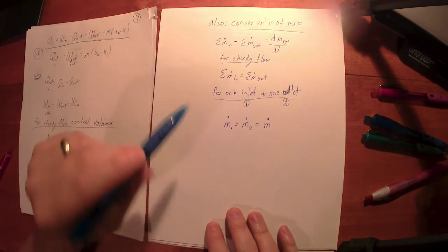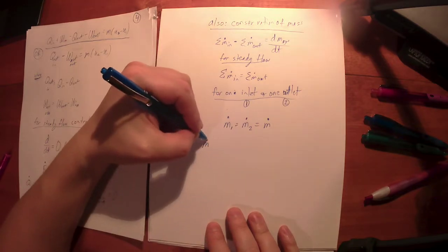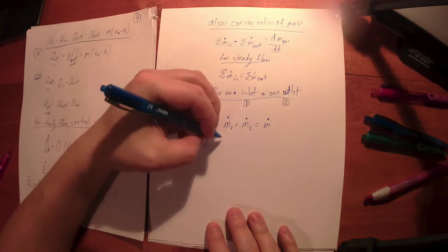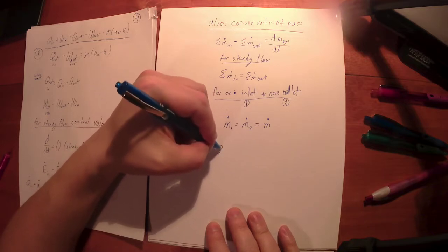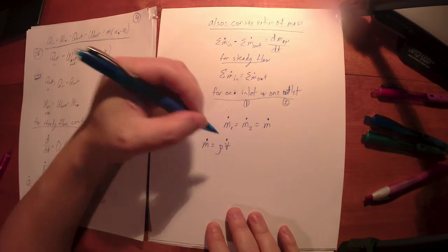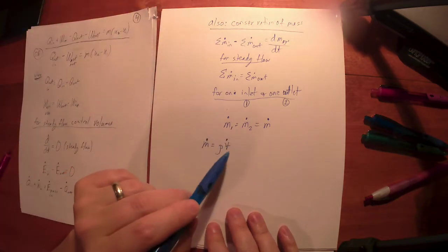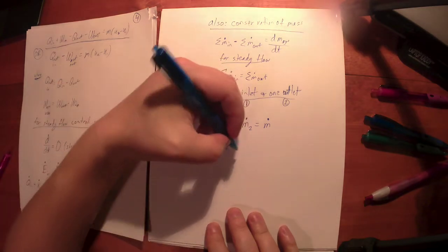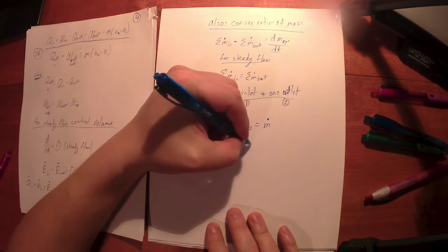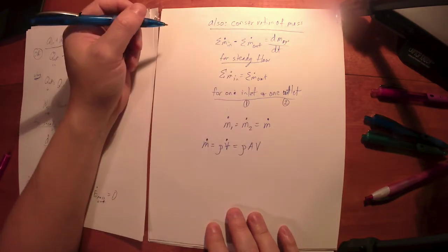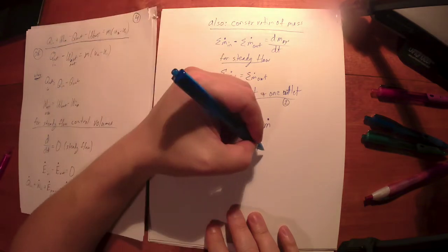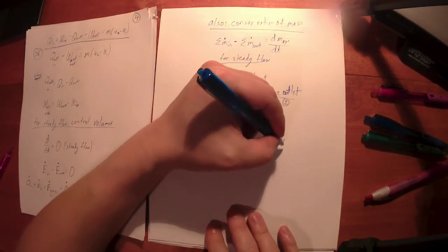Okay, so how do we find this m dot? Well, any m dot, we can always find as the density times what we call the volumetric flow rate. For us, that's V dot. Some texts will use a Q, especially a lot of fluid mechanics texts will use Q for flow rate. We use Q for heat, so that doesn't help us. So this text and some other thermo texts will use a V dot if they talk about volumetric flow rate. If you don't have the volumetric flow rate, maybe you have the cross-sectional area of the conduit and the average speed. And recall, our friend the specific volume is the reciprocal of density.